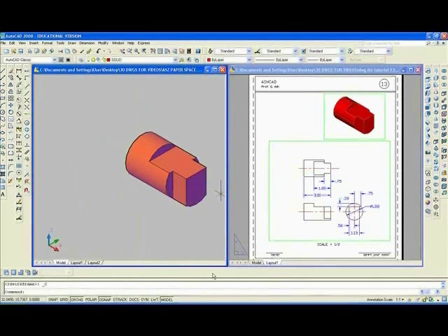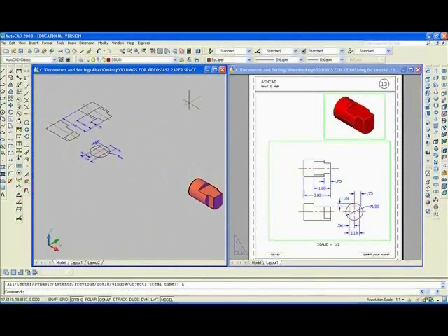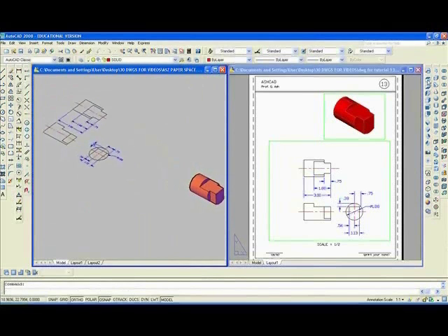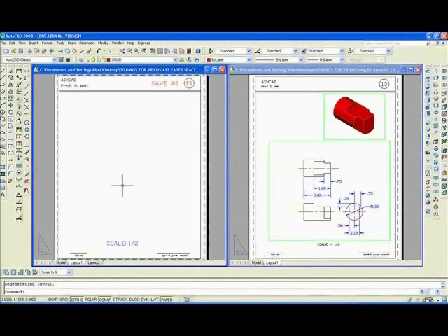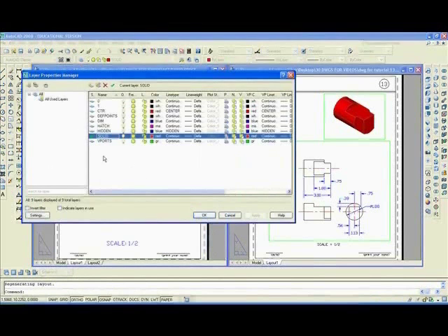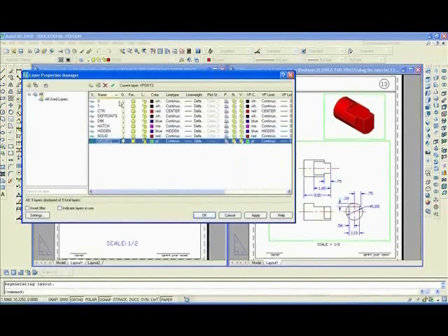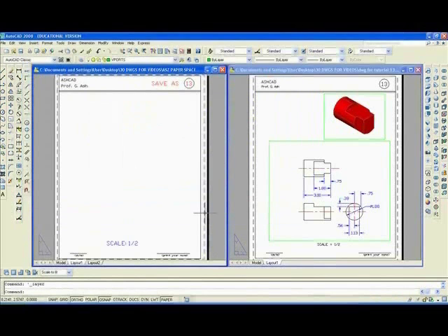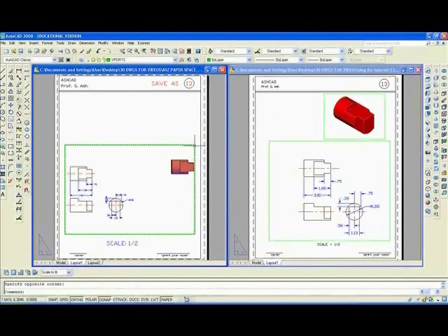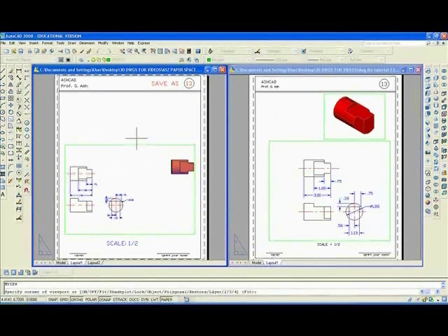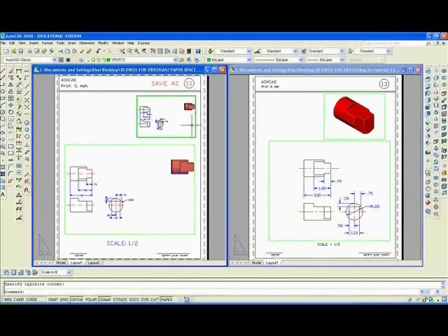Shade it, right. So now we can Z enter, E enter, go into top view, then go into layout mode or paper space, change layer, make reports current, type MV, enter, and make a big window. Repeat the command, make small window, double click,